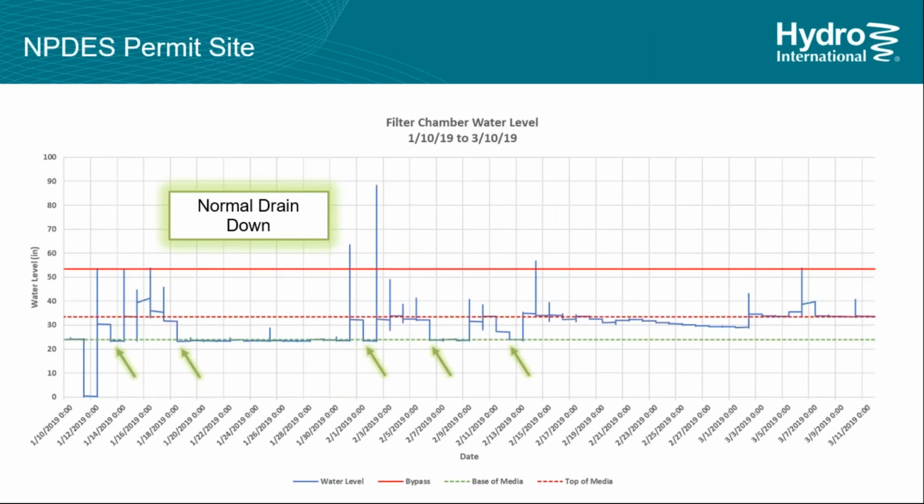And then last, we can comment on performance. Drain down is once the storm stops, how quickly does it take for the water elevation to get back to rest and drain the system down in the unit. Now, this is what a typical drain down time looks like. It's very quick, it's pretty short.